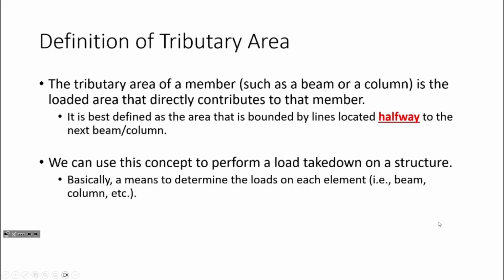That's where tributary area comes in. So the definition of tributary area is the area on a given floor space that a given member is responsible for. And it's best defined as the area that's bounded by lines located halfway between adjacent elements.